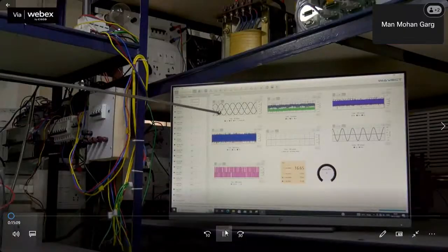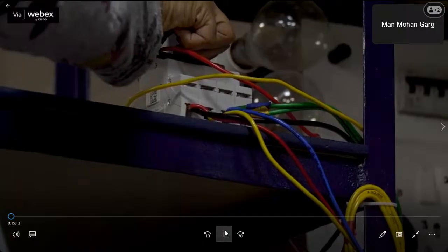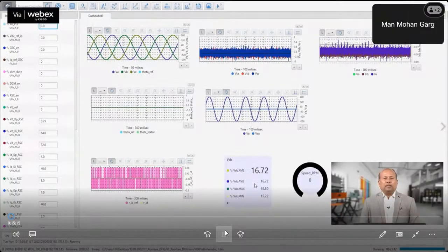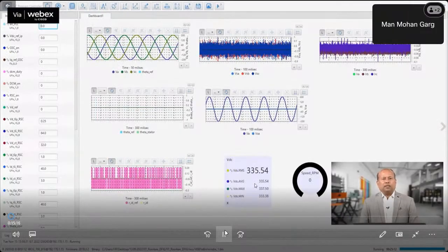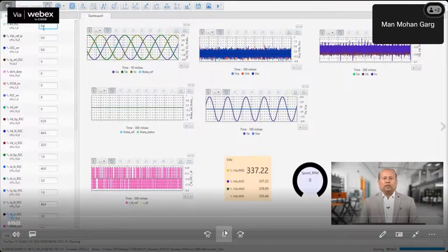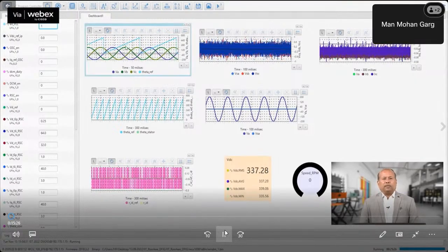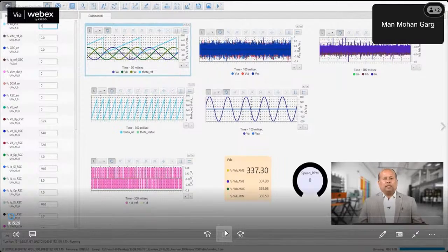The main and the rotor branch circuit breaker is switched on and the DC link is charged initially to 340 volts. Then we enable phase lock loop and check the reference theta with the phase A voltage.